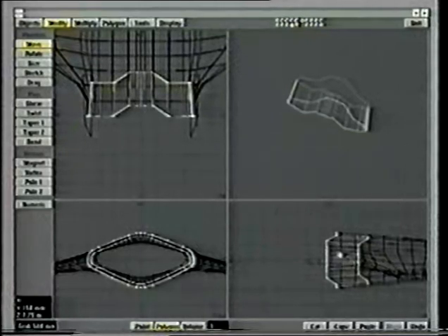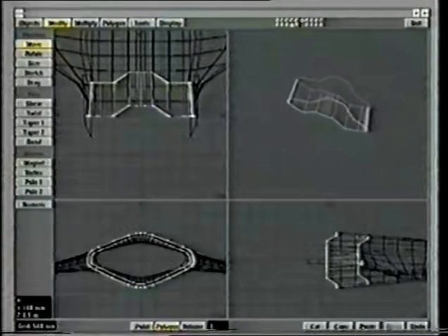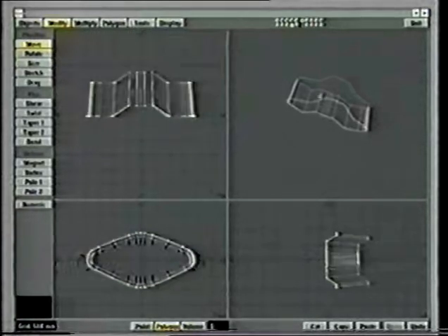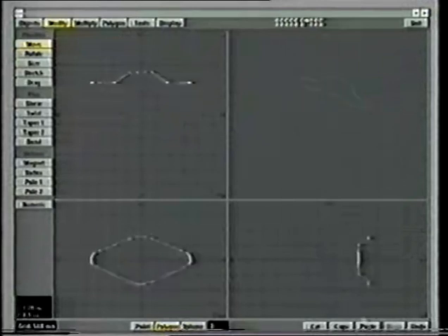That doesn't look like it's punctured the surface anywhere. The only way we'll really be able to tell is when you render it. It can be very difficult to see whether or not you've done this from the 3 view. So the other thing I want to do is cut this polygon out, paste it in yet another layer, and divide it up so it would shade properly. If you even get a glimpse of the inside and it's not divided up properly, it will look ridiculous. It'll try to smooth shade around a surface, blinking on and off. Whenever you get a non-planar polygon, it's something you don't want.